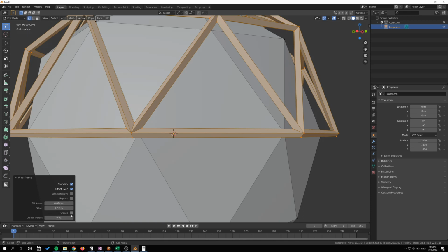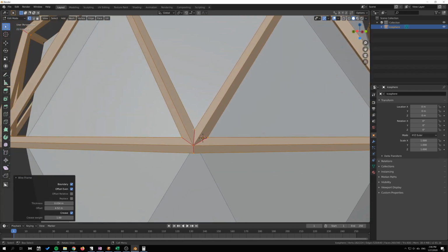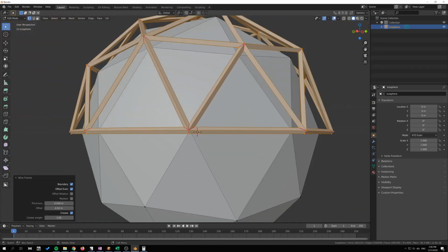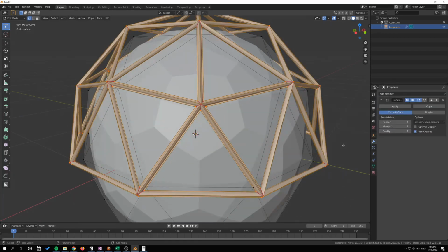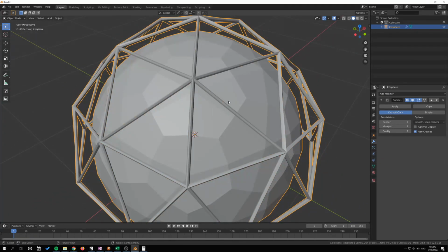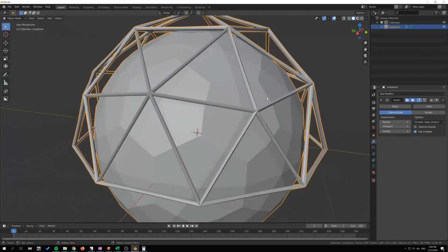And this crease here can be valuable if we are going to subdivide this mesh using a subdivision surface modifier. So let me just add this crease here and increase this value, and you will see that as we approach one, these edges at the corners will become marked for creasing. So let's just go to the modifier tab here and add a subdivision surface modifier, and it's actually getting added to both the wire here and the underlying sphere or icosphere there.